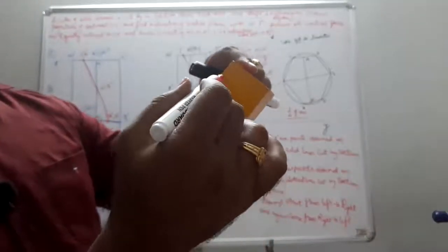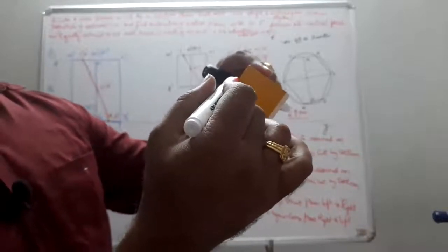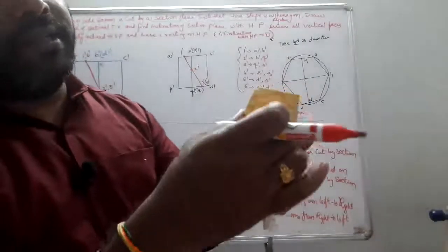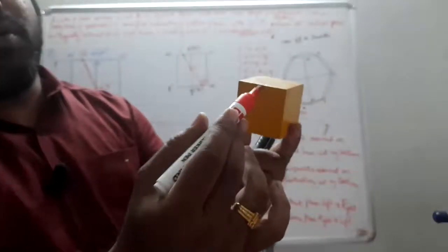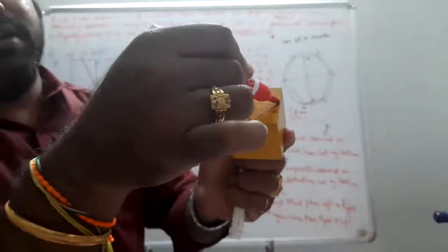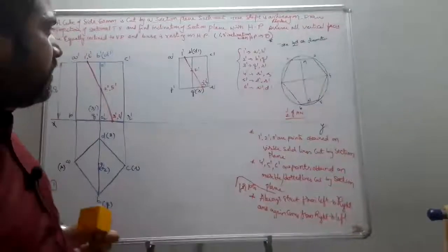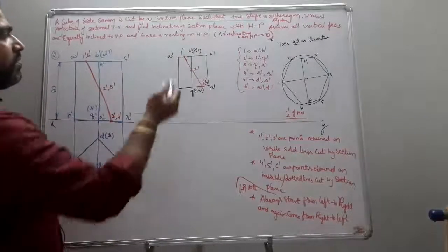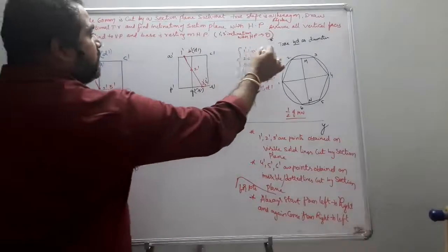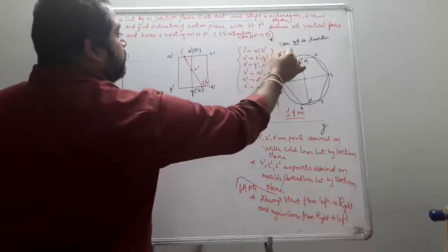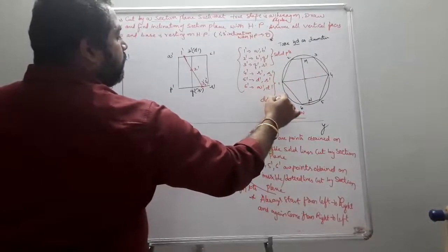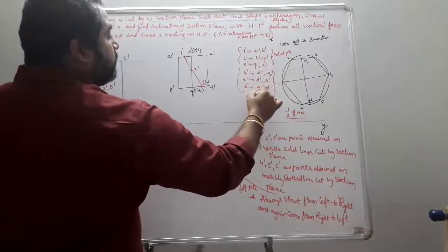Your cutting plane cuts at this. When you cut this point like this, at here you see this point only, but backside you have it. If it is cut like this, this point is seen, but when you see from front, it is not seen. Okay, let us see. A dash B dash is seen. AD edge is not seen. That was the hidden points. So these are the solid points. These are the dotted or imaginary points.